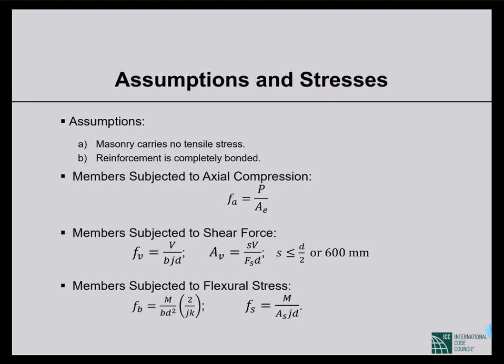Now the formulas for calculating stresses are simple, the same as the RC formulas. For axial compression, it is force divided by effective area. For shear, Fs is equal to V divided by Av jd, or Av Fs d over s, the same formula. All the formulas are similar to reinforced concrete formulas.